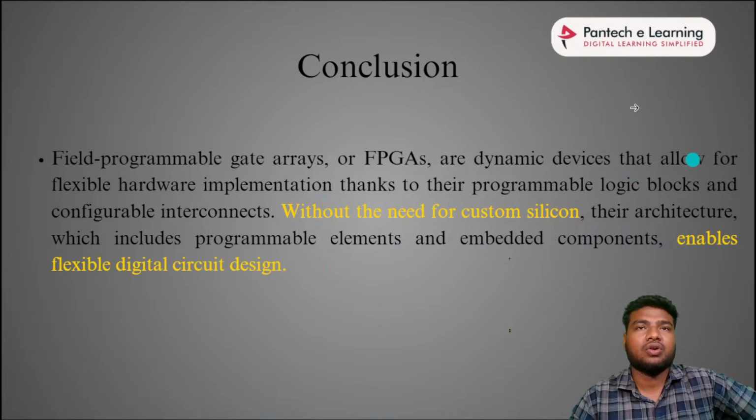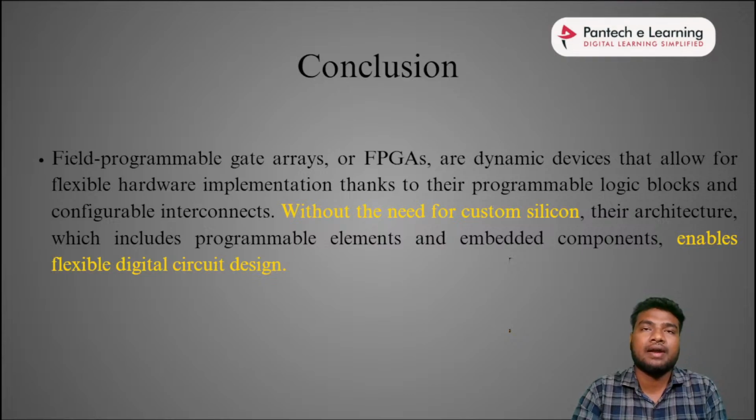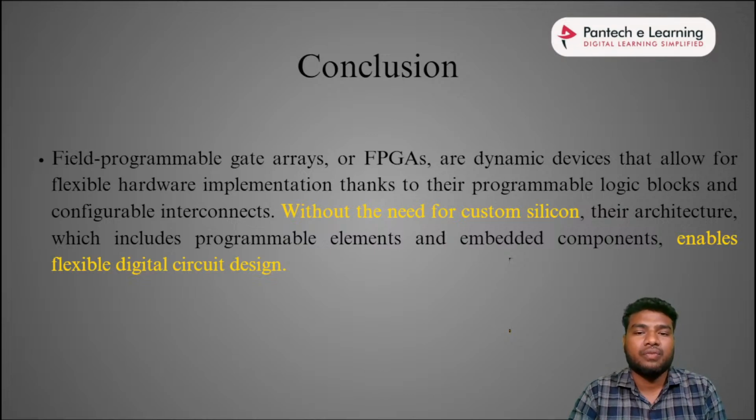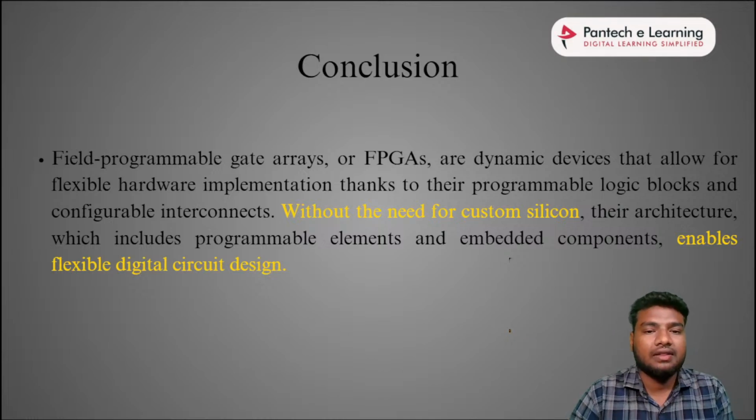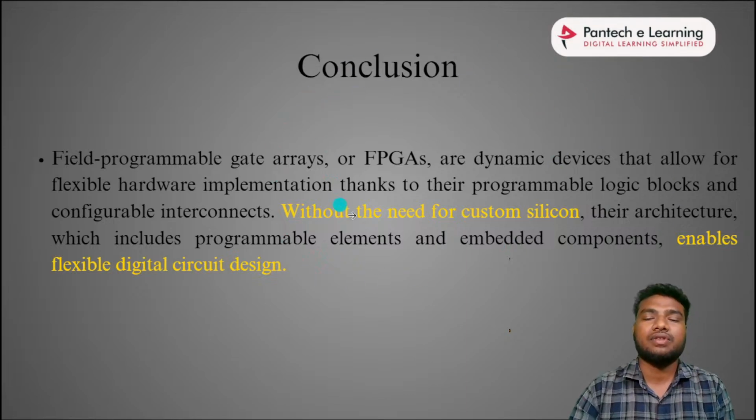Coming to the conclusion, you have to keep in mind that every FPGA board consists of a matrix of CLBs or LABs, logical array blocks. Xilinx consists of CLBs, and Altera FPGA consists of LABs. Each CLB consists of a lookup table, mux, and flip-flops. Based on these three things, we can do arithmetic operations in the FPGA. The lookup table is for combinational logic and the flip-flops are for sequential logic. Combinational logic is processed in the lookup table, and sequential logic is taken care of by the flip-flops inside our CLB. This is the thing you have to be aware of in the architecture.